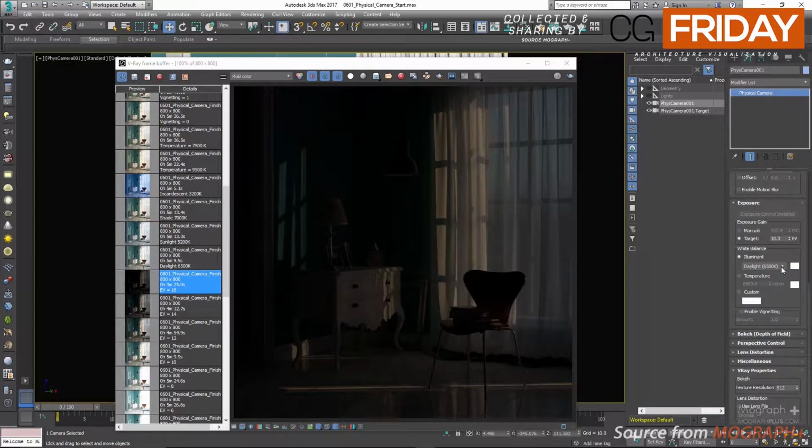In Kelvins or K, the lower the temperature, for example 3200 K, the more red the light will be, and the higher it is, for example something like 9000 K, the bluer the light will be. Now if you take a look at the presets, you can see, for example, we have incandescent 3200 K. Obviously an incandescent light source will cast a very warm reddish light that makes the white colors look another color in the photo taken by a camera or in your renders. Unless this is something that you want, you can white balance the scene by setting the preset to incandescent 3200 K, and by doing so we cast out that warm red color temperature and white balance the scene.